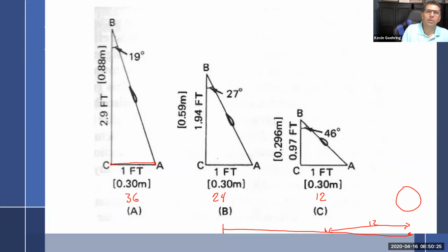So remember the blade's coming around, the aircraft moves forward 1 foot, the blade is going the same RPM, and it came down. I want to say for every 1 foot the plane moves forward, the prop at station 36 rotates 2.9 feet.